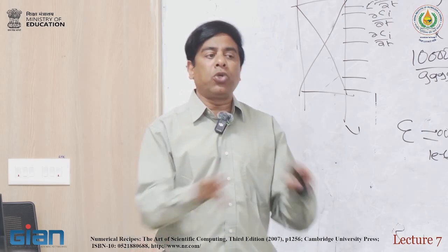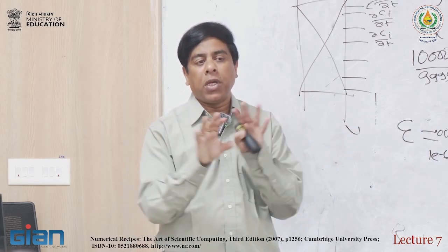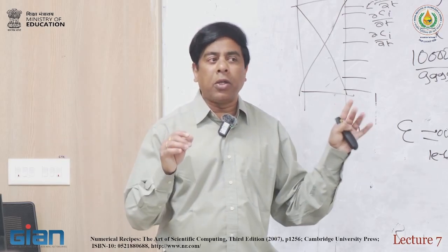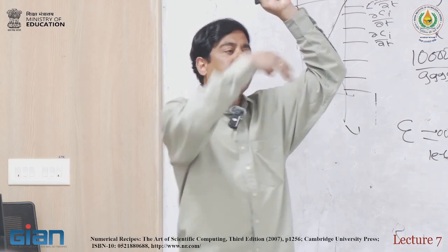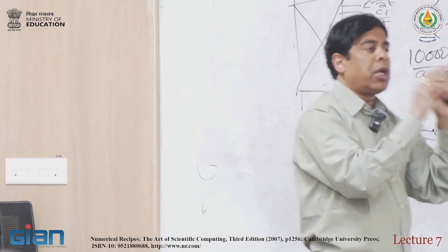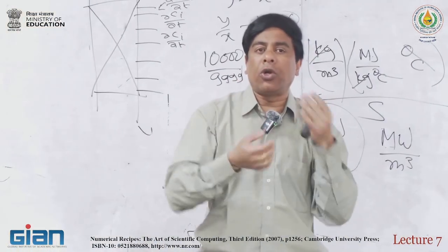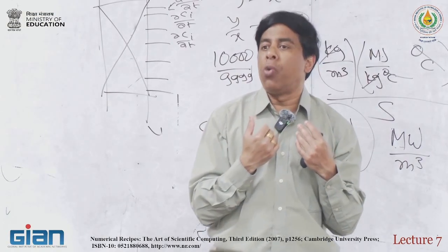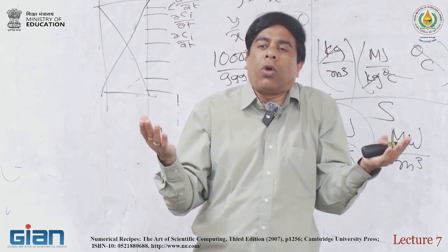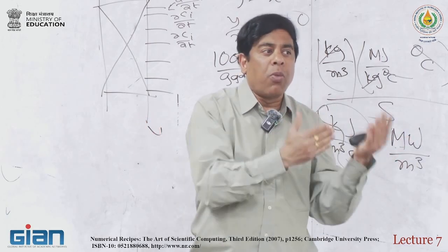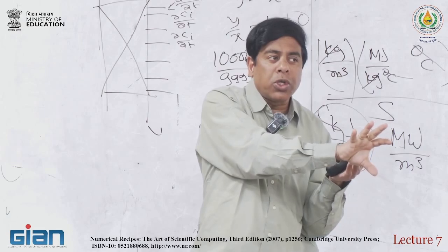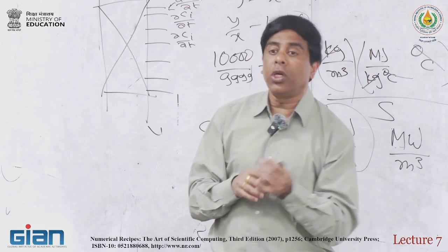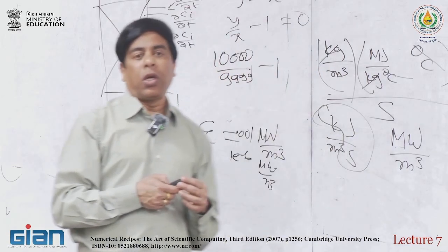If I'm normalizing them, that basically means it's a fair game for all equations. It's not like the pressure drop equation, because I did it in Pascal, always keeps popping up because it cannot solve it, while I decided to do my energy in terms of gigawatt or megawatt, and I can easily solve it. That's not a fair comparison. I'm solving one equation to very high accuracy, but neglecting the other one. Those are other tricks that we need to think about.